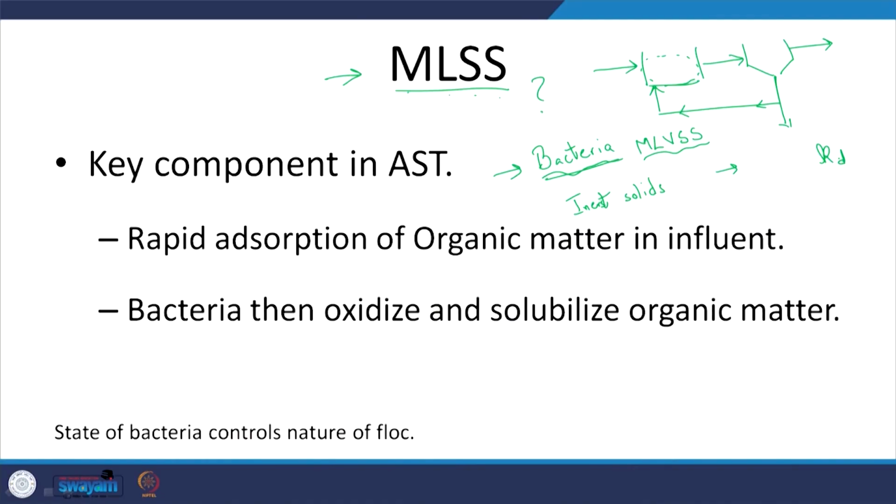And you will have dead cells, free swimming cells, or the motile cells, if I can call them that. So you'll have a complex ecosystem in this MLSS. So what happens to the waste that is coming in? The waste that is coming in will be immediately absorbed, or adsorbed, by this MLSS. After that, the bacteria will oxidize, or solubilize and then oxidize, the organic matter, right? So that's how it's going to work. So we are going to call the contents of this tank MLSS, right?